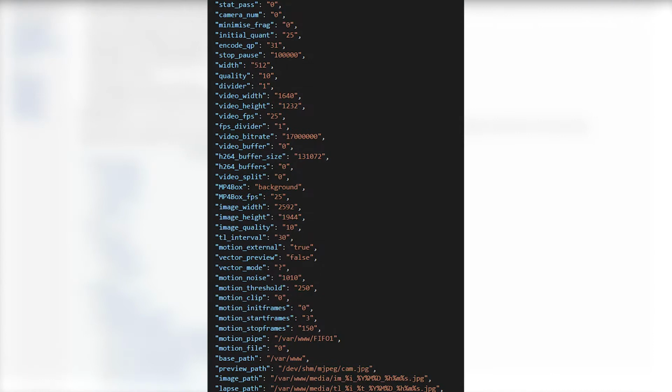For this use case, it's configured to capture images at a specified frame rate and put the captured image into a RAM buffer. This RAM buffer is of course much faster than saving to the SD card and allows us to continually access the image in the RAM buffer and send it over the air to the connected device, giving us the perception of a live video. Now there are a lot more things that RaspiMJPEG can do, but this is its core functionality.